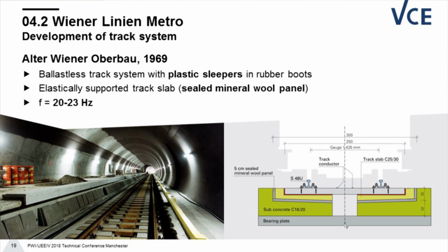So it has a monoblock sleeper loaded on plastic boots on a concrete plate, and the concrete plate was again loaded on an element that was a sealed mineral wool panel. It was sealed because, of course, the impact of water should be prevented. However, it turned out after 25 years that this sealed mineral wool panel was not perfectly working and fulfilling the long-term behavior that was expected.